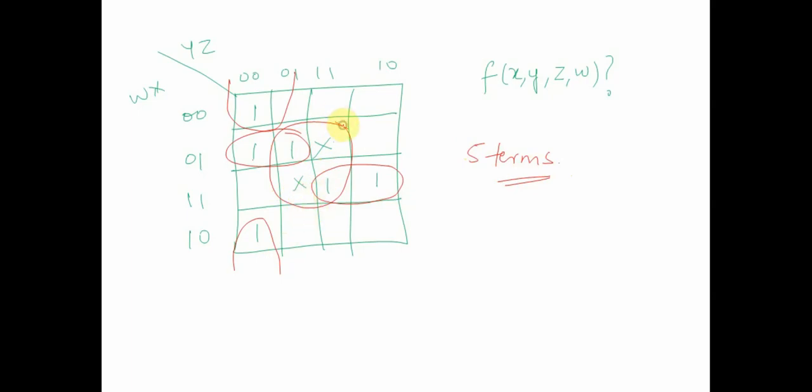For example, if we don't include these X terms, we will have fewer terms. Over here, we ended up adding how many terms? 1, 2, 3, 1, 2, 3. So actually, it's not 5 terms, my mistake, it's 4 terms. In this particular example, the don't cares are not helping us, because they help us form a bigger group, but inadvertently we have ended up creating one extra grouping which is not at all required if the X's would not be there.